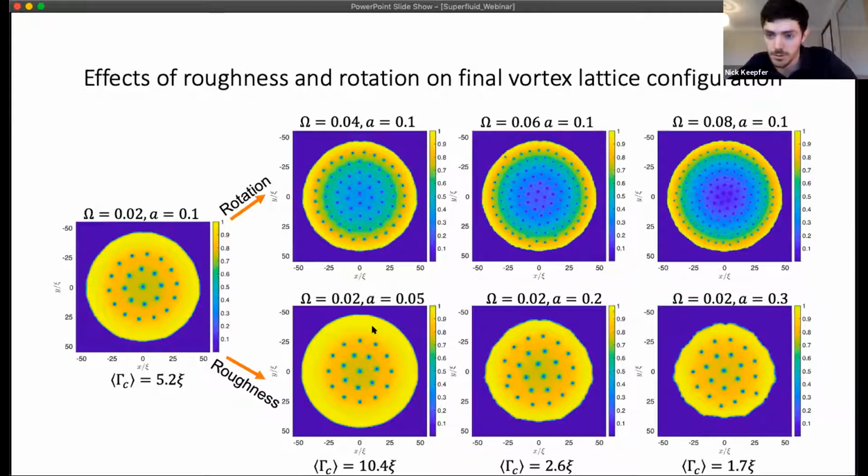And this is a predicted result. It hasn't been found before. It was predicted back in the 70s, but no one's really done a numerical simulation to validate it. And this is the first evidence we see of it. As you increase this A parameter and therefore increase the roughness with it, you start to encroach more and more into the fluid space. And you get to a point where your boundary encroaches so much on the fluid, you actually restrict the development of vortices in that edge zone, and you minimize the vorticity in your system because you're leaving it less room to develop the vorticity within.